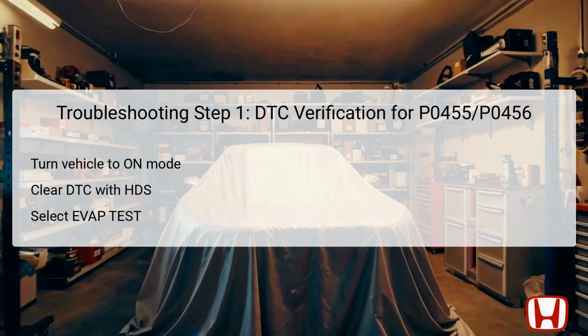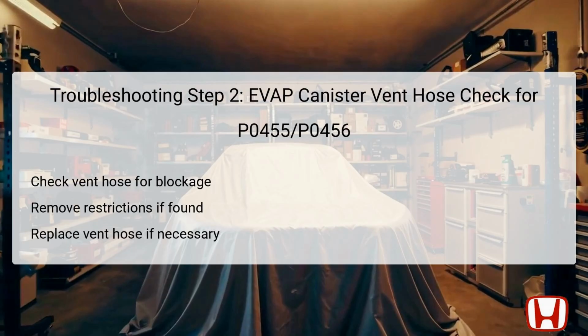in the troubleshooting process. The second step involves examining the EVAP canister vent hose for any blockages or restrictions that may impede airflow. This hose is crucial for allowing fuel vapors to vent properly. If any obstruction is found, it must be removed to restore normal function.